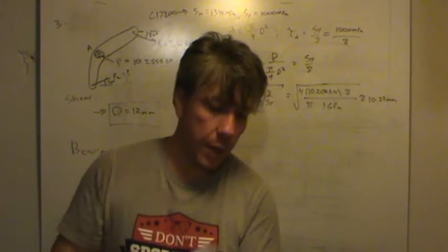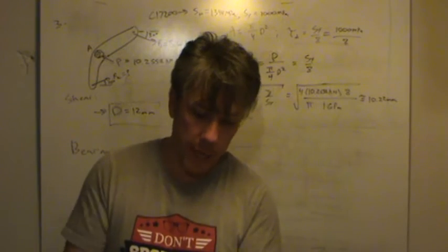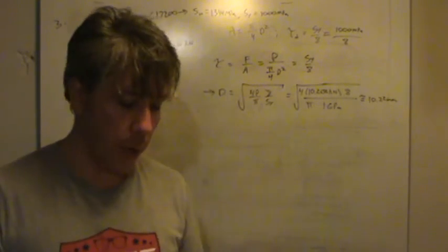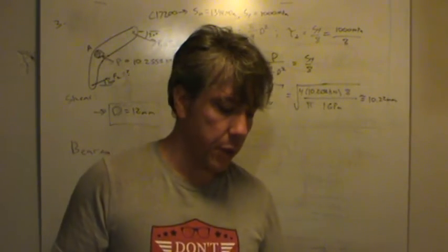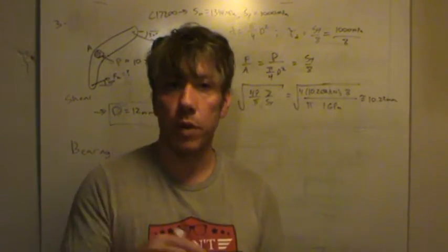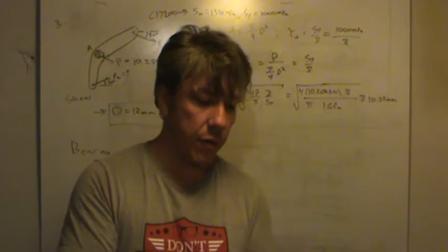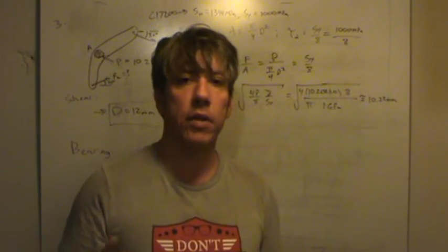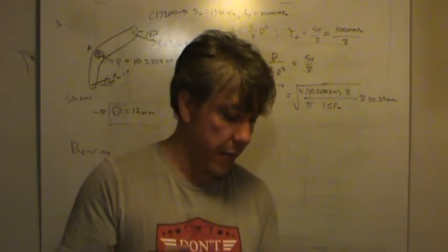Yeah, here we are. Page 147 and 149 essentially. Bearing stress, equation 3.20. Bearing stress is computed in a similar manner to direct normal stress. The bearing stress is the force over the bearing area, but you have to be careful because the bearing area is something you have to consider. In fact, on the next page,